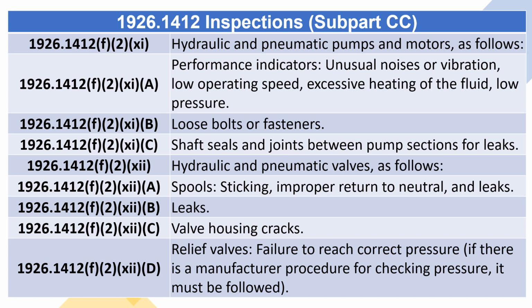Hydraulic and pneumatic valves, as follows. Spools: sticking, improper return to neutral, and leaks. Leaks. Valve housing cracks. Relief valves: failure to reach correct pressure. If there is a manufacturer procedure for checking pressure, it must be followed.